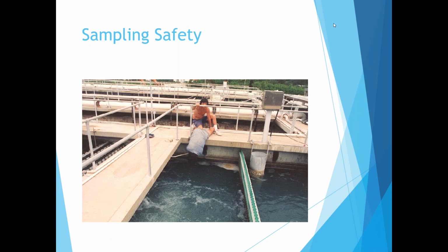But again, talk to your permit writer, talk to your lab. This is just one of those things. Again, this is wastewater. This isn't a chemical plant where the exact time down to the second matters because you're producing a drug. In wastewater, we deal in big batches, things that don't change at the turn of a hat. Now, you might have a clarifier that burps, but even that's going to turn over a lot of flow over a sufficient enough time to be notified, collect a sample, and do something about it.